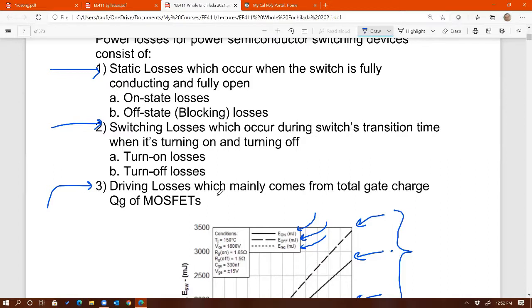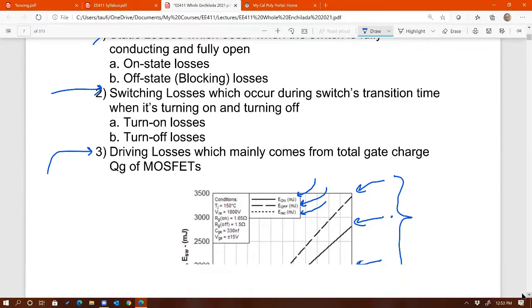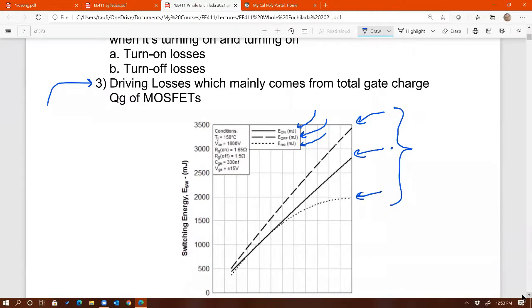Magnetic losses means these AC losses from magnetics, right? Such as skin effect, proximity effect. What else is there? Hysteresis loss, and then what's the last one? Eddy current loss, right? Those are really involved in terms of math. That's why I don't usually include those in the first phase of the design. Okay. Any question on that?